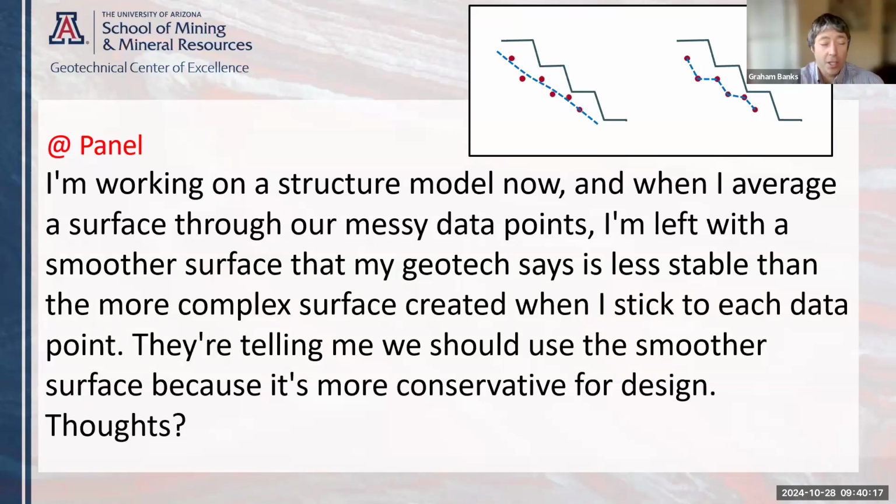One more consideration is who collected the data and why were they biased to those data points? Is it because of the availability of seeing outcrop versus soil, or how much time did they have? And so we don't join the dots because the dots are biased by the human. So it's a zone of damage. Most faults are. Call it a shear zone, call it something like that, but it's not a surface and it's not joined dots.